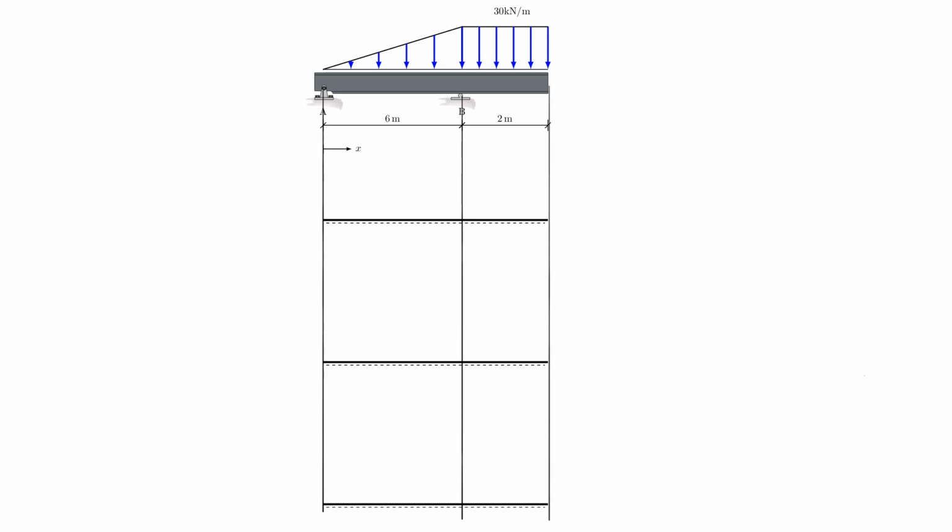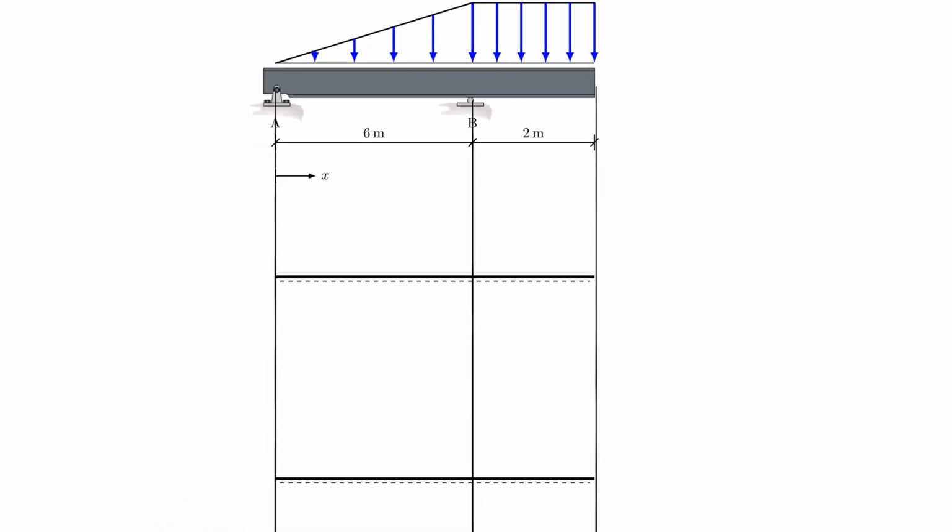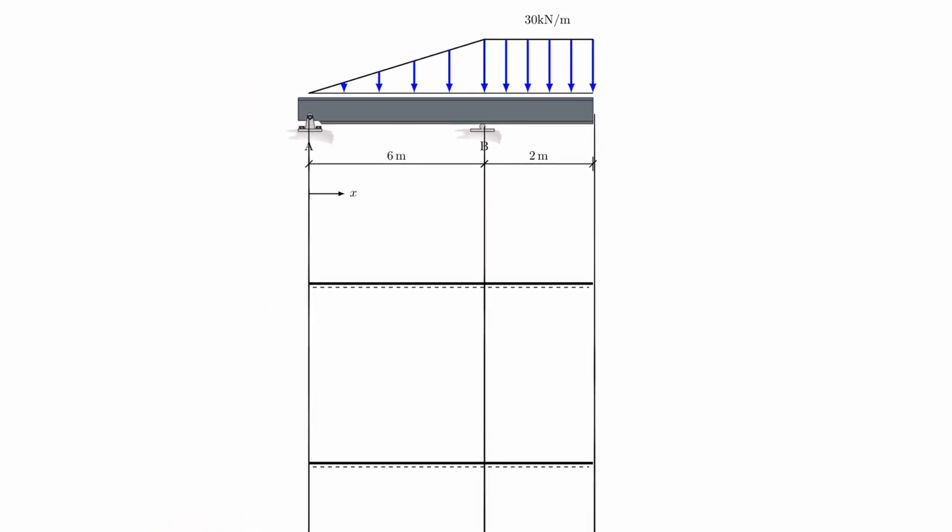And my plan is to put the normal force down here, which happens to be in kilonewton in this case. And of course we know it's 0 and 0, so I need to indicate that, and then I can go ahead and include my shear force and my bending diagram.